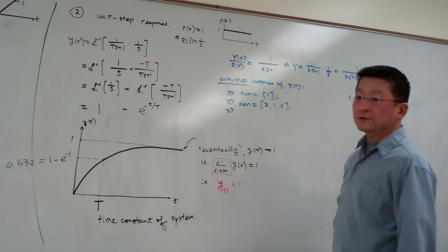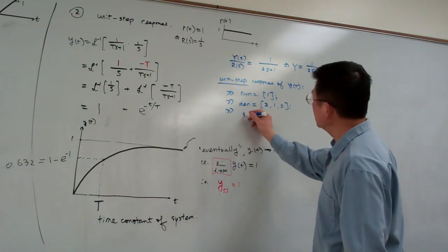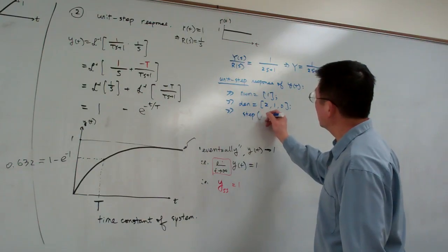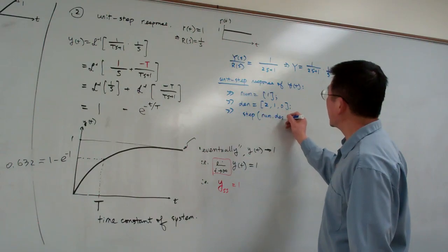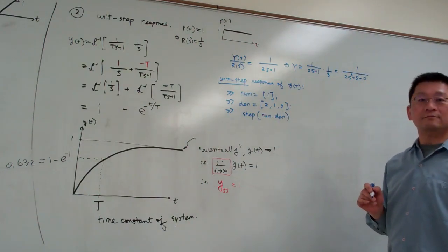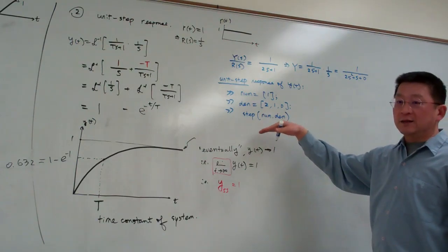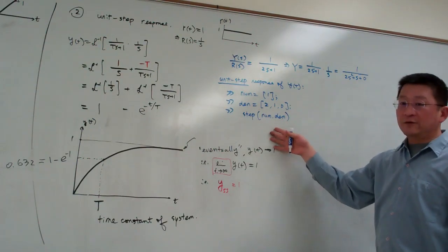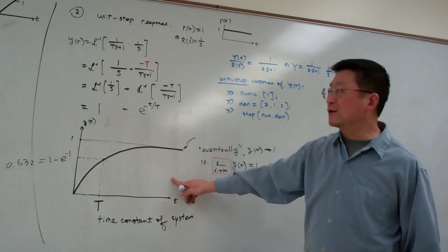And then you're going to use this command for step, numerator and denominator. So after you hit return, MATLAB will give you a certain curve similar to this. Okay.